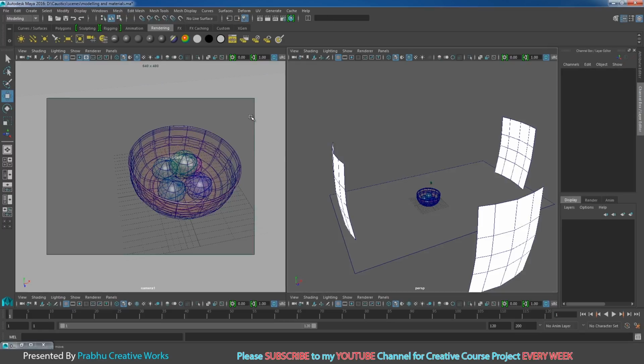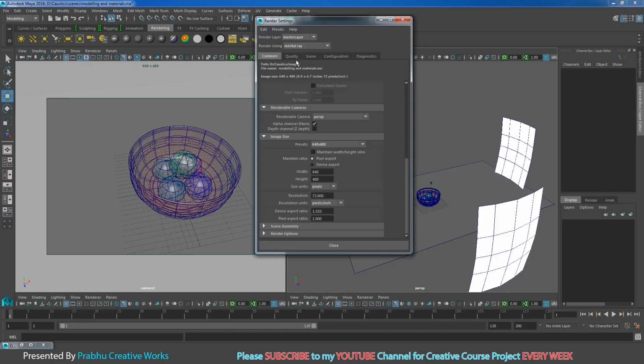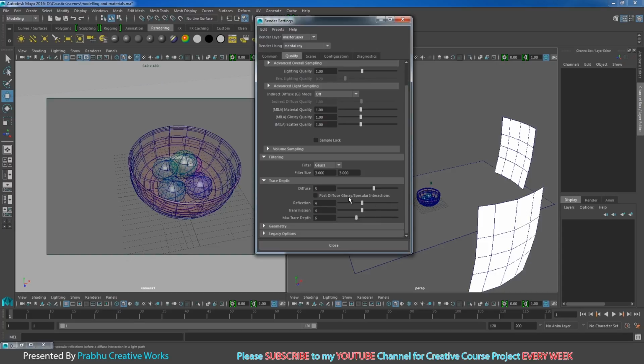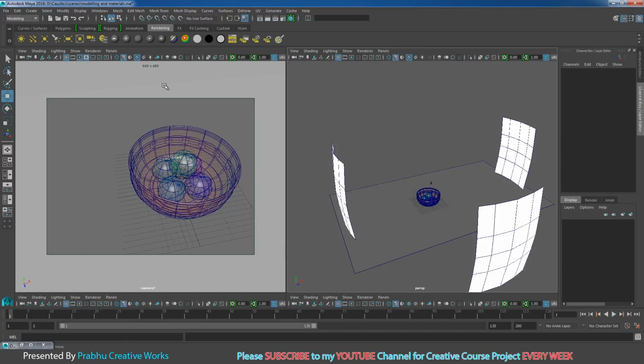So by default I want to check my render. Go to render settings, go to the quality tab and turn on show advanced settings. Go to trace depth and set reflection 1, transmission 1, and maximum trace depth 2. We will increase these manually when we take the final render. So I will select this viewport and click the render button.